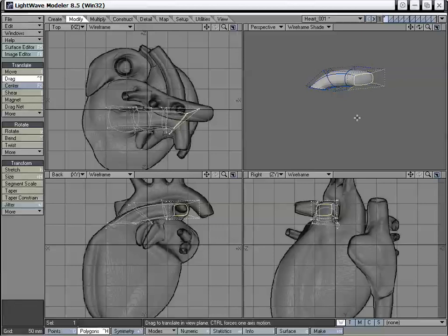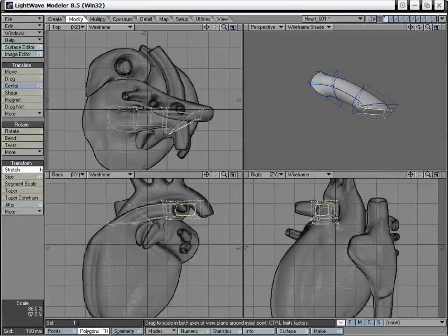And there's many different ways to do this, but this is something I prefer because it's nice and quick. And with a little bit of tweaking, it looks alright. Shift F once again, right mouse click, H, and I'm going to stretch that inward. And you'll notice too, see how we had it before, where that was kind of set up perfectly, now it's off. So you want to make sure you don't do any of your major tweaking until after you get your next extrusion laid out.